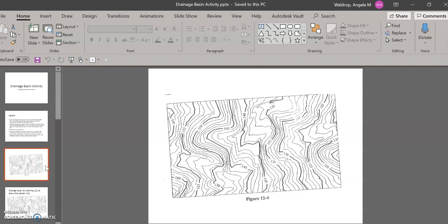This is another picture of what the drawing should look like when you open it. You should see curves that look like this with the appropriate contour labels. There may be distinction between certain contour levels. For example, every contour layer that is a multiple of 5 is a certain color and thicker, so it can be easily found. This is generally a good practice to follow when you're working on contour drawings.